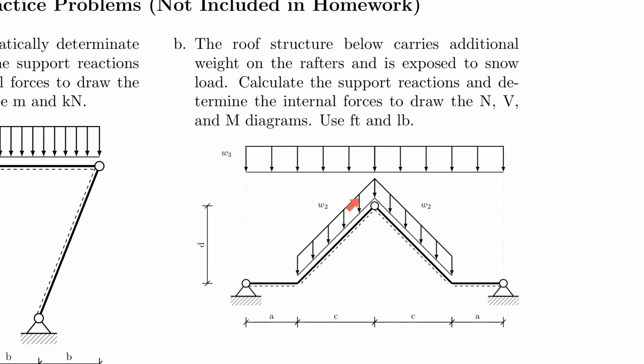So first of all, we have a superimposed load case. We have self-weight here, and then we have snow load on top of it. But we also have a non-right-angled corner that has no hinge in it. So you have not seen this so far in this class. We only had corners like here that had a hinge and then were not orthogonal. So what this means here is that the shear force and the normal force at the corner need to be translated under the given angle. Whatever angle these values give to you, C and D produce a certain angle here to the horizontal. And so that leads to a transmission of the shear force and the normal force at that corner.